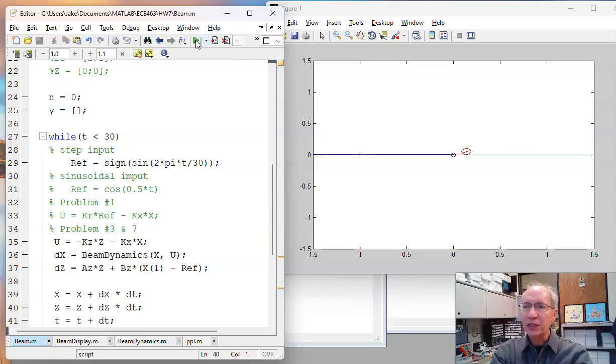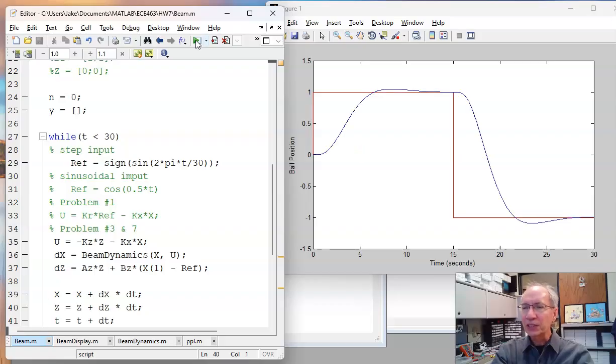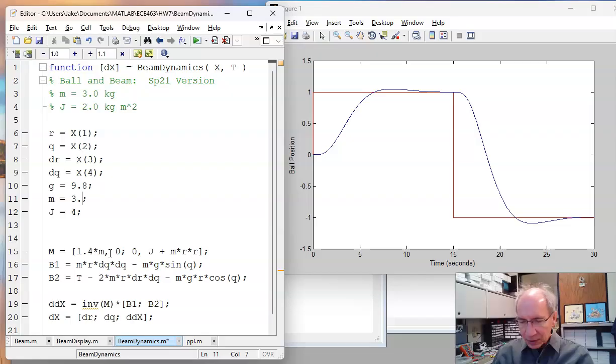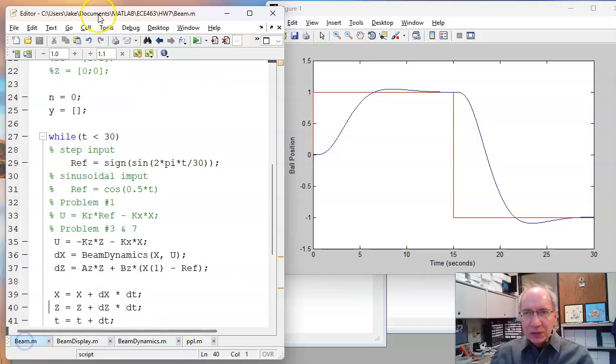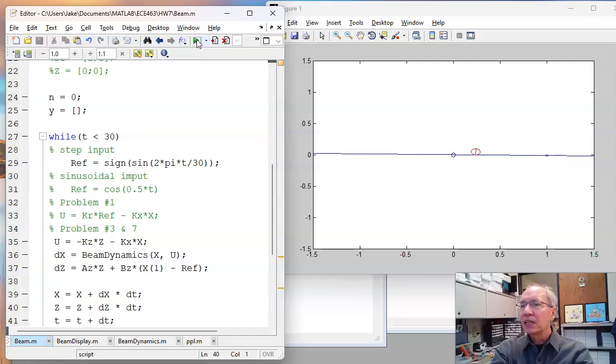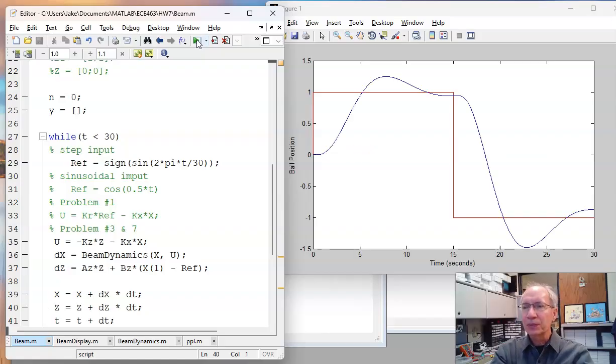The integrator tries to figure out what input I need, what constant holds the output, holds the error at 0. And at 2.8 kilograms, it figures it out. Works great. Let's go back and try 3.5 kilograms. Now that was unstable previously. If it's 3.5 kilograms, again, that's the integrator trying to figure out what torque I need to hold the output. It eventually figures it out, forces the steady state error to 0. That's what the servo compensator does for you.